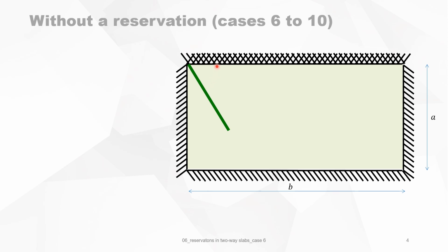Maybe later on we will make a more detailed calculation to calculate this angle. But for the moment we will take the 30, 60, and 45 degree rule. That's also 60 and 30 degrees, and where the two sides are simply supported, it's a 45 degree angle. Then we connect the yield lines, and because we have a fixed end, there's also a yield line along that fixed end.